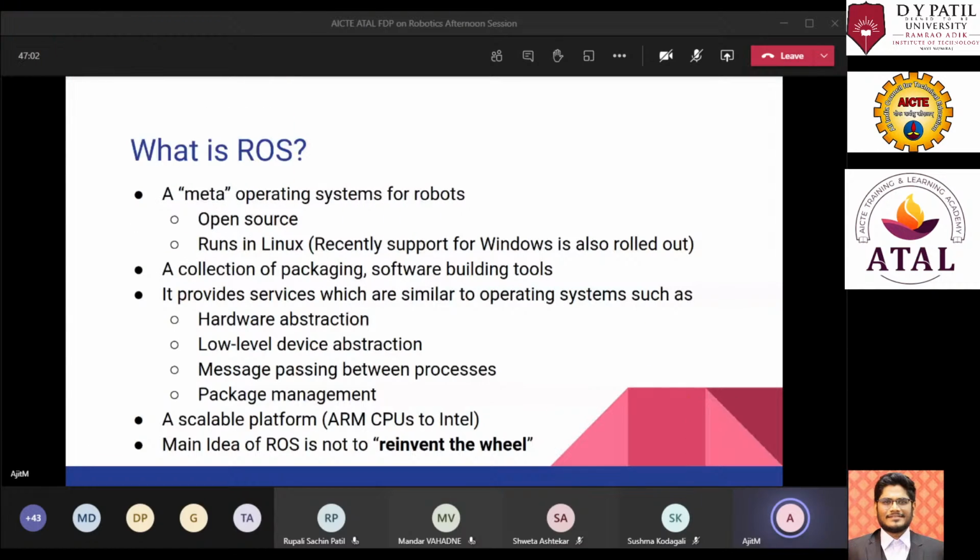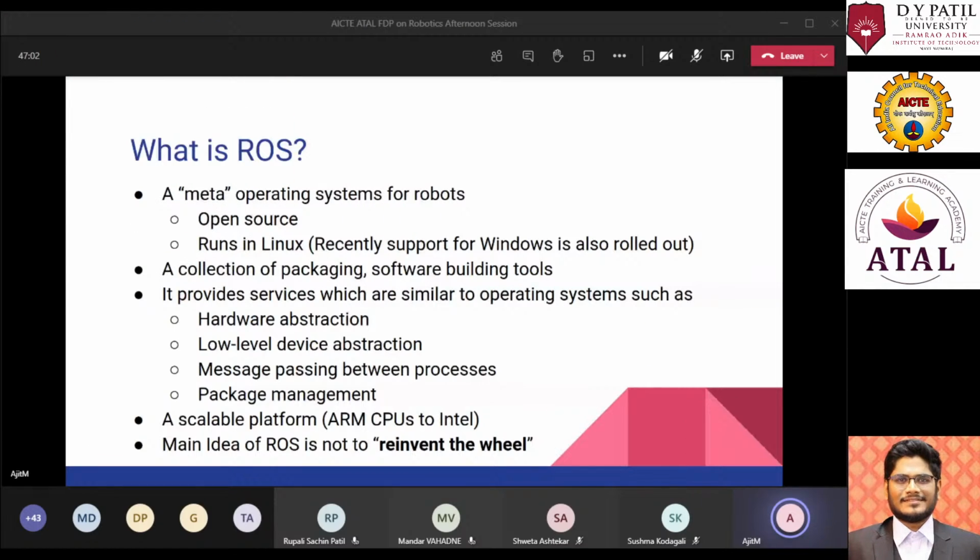For this, ROS is an excellent architecture because it provides you with the ability to create nodes. It gives you a message structure to pass the incoming sensor data to other nodes which are present in the system. It also provides sensor libraries for interfacing. So if you have a GPS sensor, which is an I2C based sensor, which communicates on the I2C bus, you have those libraries as well to interface with the device and with the main computer.